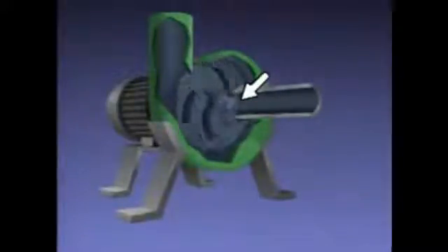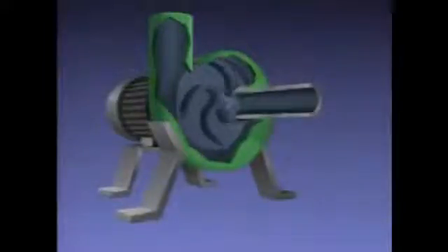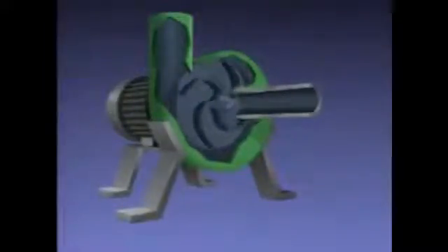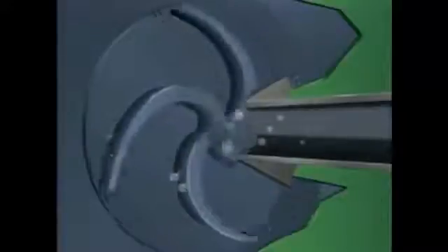Cavitation normally begins in the suction of a pump, where the pressure is the lowest and liquid is drawn into the pump. If the pressure of the liquid decreases too much, the liquid will vaporize or boil. When this happens, bubbles form and travel with the liquid in the pump. As thousands of these bubbles travel toward the higher pressure areas in the pump, they are compressed until they can no longer withstand the pressure and collapse or implode violently.